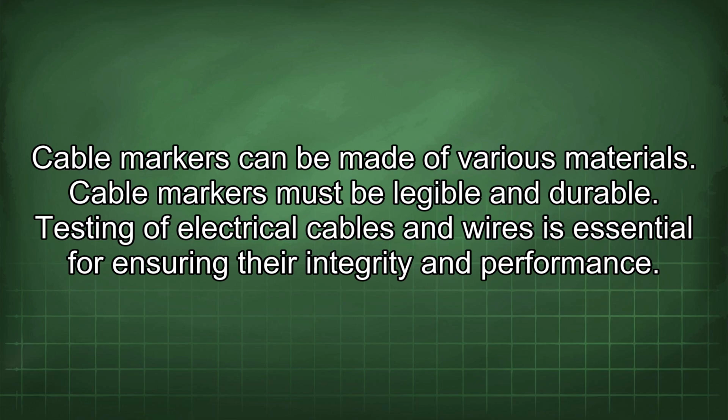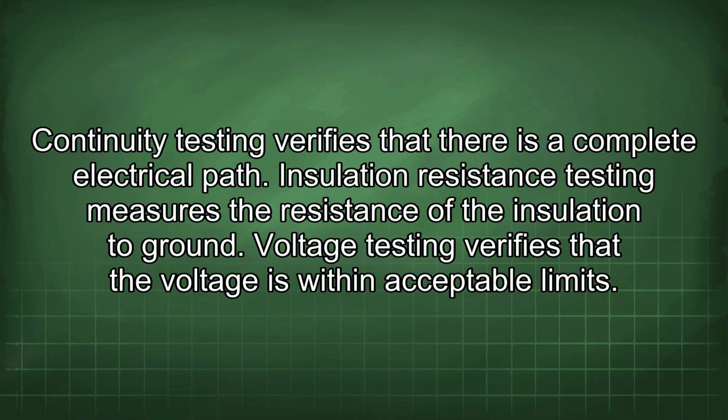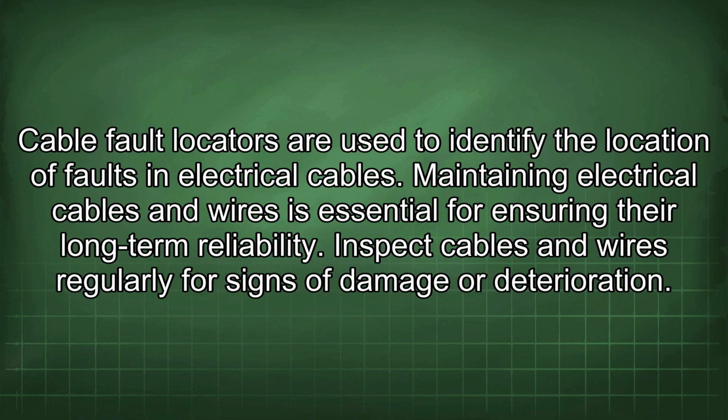Testing of electrical cables and wires is essential for ensuring their integrity and performance. Continuity testing verifies that there is a complete electrical path. Insulation resistance testing measures the resistance of the insulation to ground. Voltage testing verifies that the voltage is within acceptable limits. Cable fault locators are used to identify the location of faults in electrical cables.